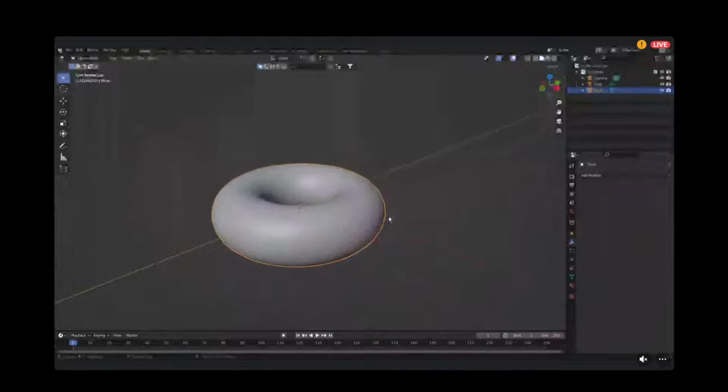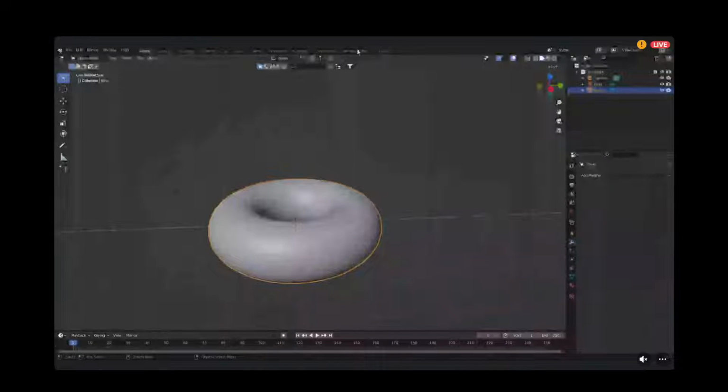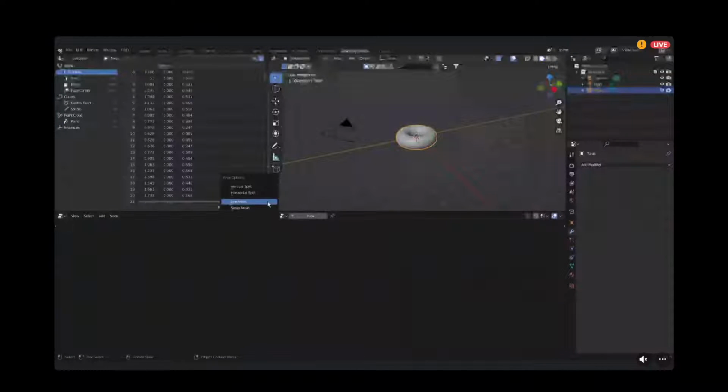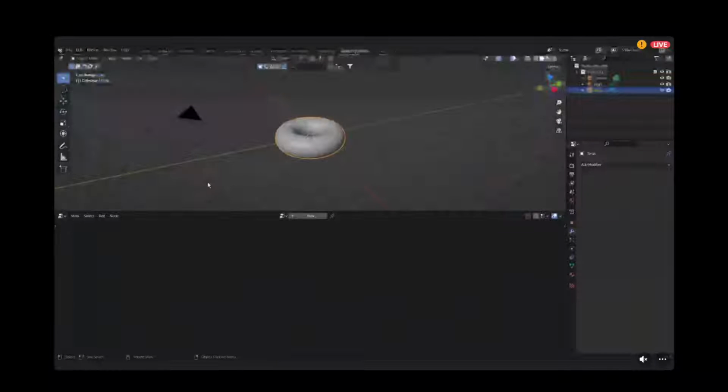What we're gonna do now is go into our geometry nodes tab over here, and depending on the version of Blender that you have, you're gonna see 3 windows open. I want to close this window because this is just to evaluate your geometry. So I hover over the junction of these two windows, right click, join areas, and point my arrow towards the window I want to disappear. So I'm going to join that, and I want to click new.